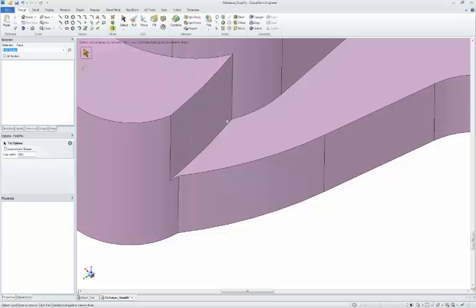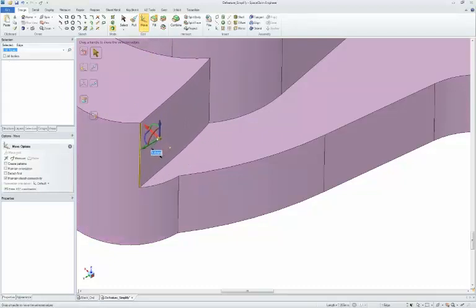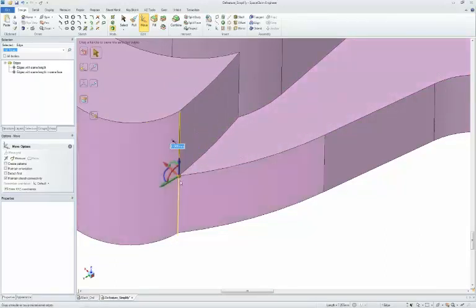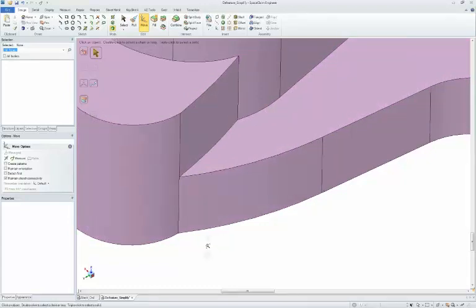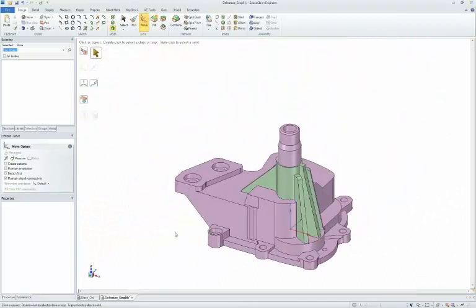You could sketch a new line to connect them. You can just move geometry on the part in the model. So if I want to move this edge to change its position, sure. Move it to a new location, or move it up to the point, covering that up, making sure we have four edges coming together at this one point in section. So again, a lot of different ways we can clean up these models for meshing.